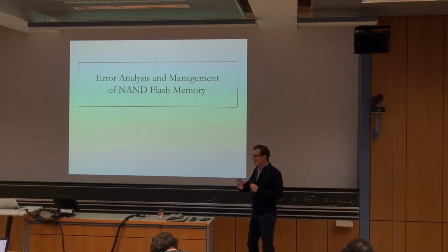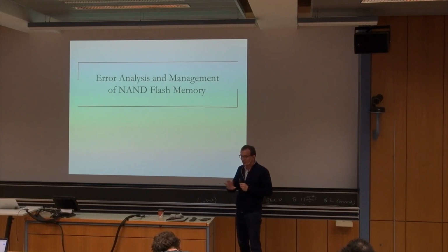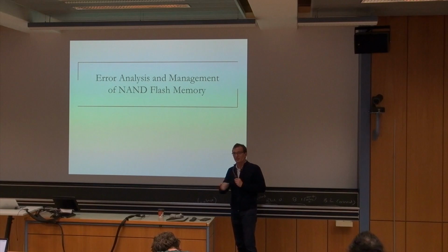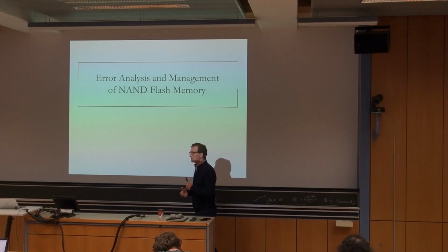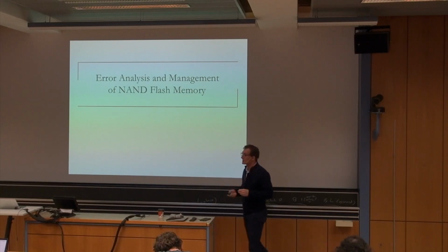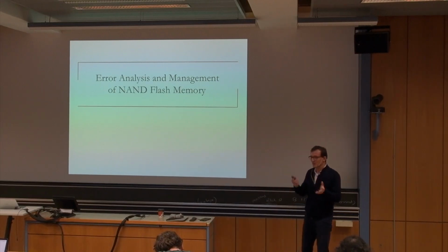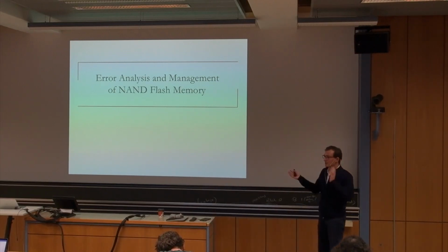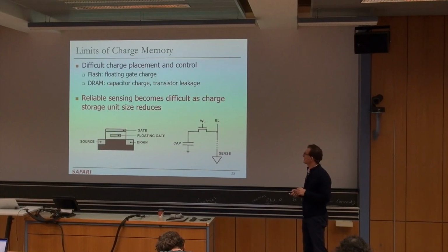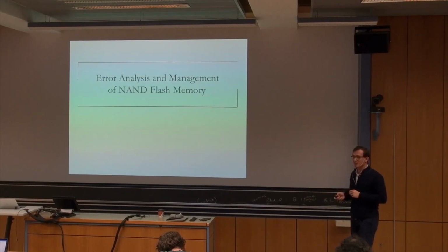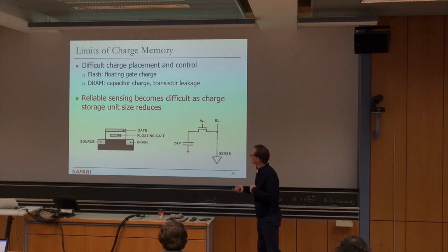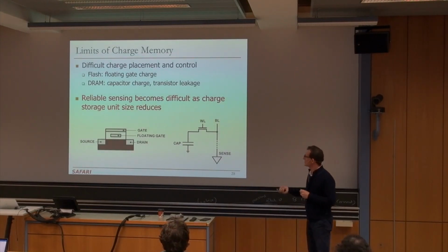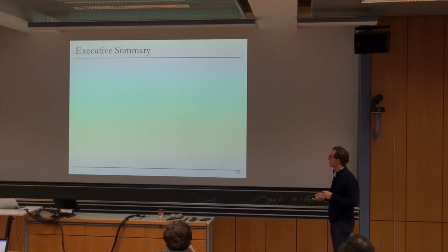They try to make sure that while things are idle, if they happen to be idle, they erase as many blocks as possible, such that those are available for writing later on, but that's not always possible, of course. They try to minimize interference. So these are some of the issues that you should keep in mind, but we're not going to talk about all of them at the same time. But let's talk about errors, because this is actually a fascinating area. And you know this picture before. Flash memory is charge-based memory, so it's prone to a lot of errors because of charge.